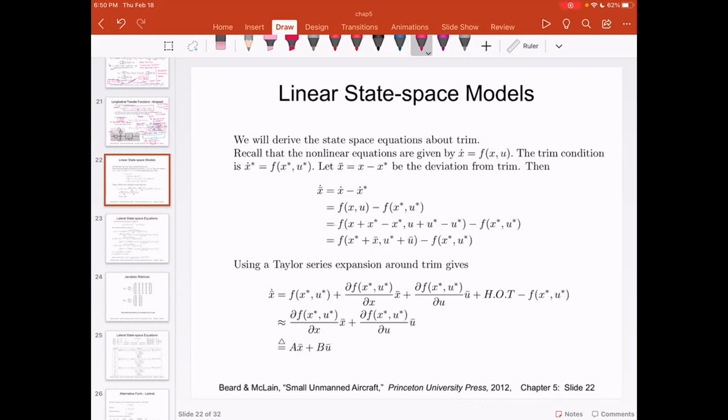Yes. Okay, Zubir has another question. Aren't the sliders we adjusted a controller? Yes, that observation is correct. But what we did was open loop control. We looked at the plane, and then we sort of guessed and tweaked, custom tuned our sliders so that the aircraft got into level flight.